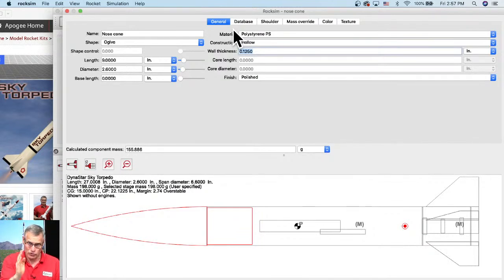It's not about altitude, it's about how the rocket reacts to the wind. Because what these numbers change is the moment of inertia of the rocket. The moment of inertia is a resistance to being moved. If you have your moment of inertia right, then when the wind hits the rocket in the simulation, a high moment of inertia means it doesn't want to move, and that is going to affect the trajectory. If there's no wind, any of those three methods is going to give you the exact same result.